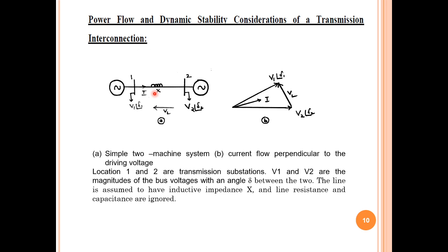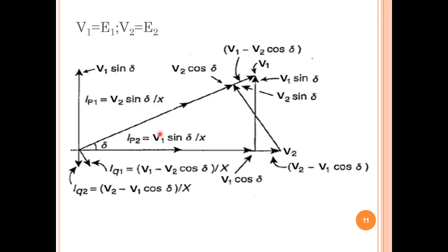Yeah, I'd like to neglect capacitance here. Let it be. If I'd like to plot one phasor diagram, maybe like this. This phasor diagram is nothing but, remember the basic line. Take V2, V1 leads V2 by an angle of how much? Delta, the load angle. Just observe this. It's not a complicated issue, but try to observe clearly. We can easily understand this part.